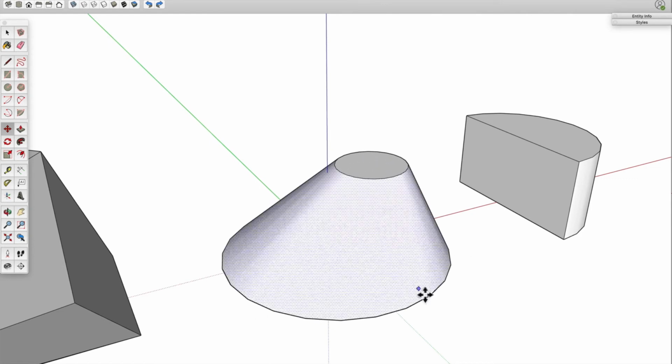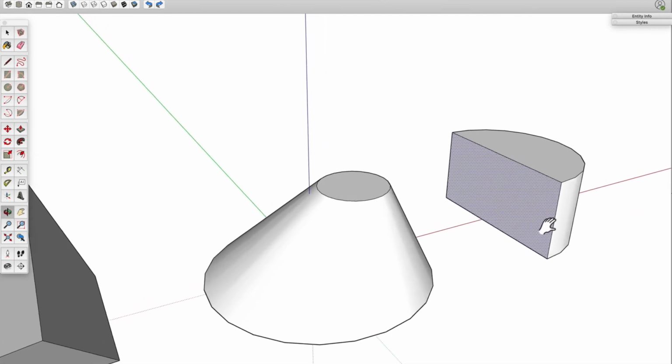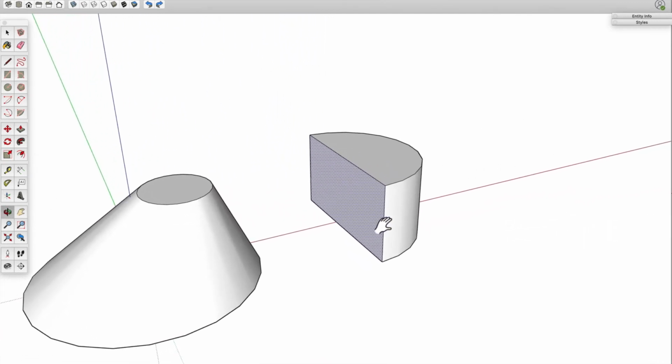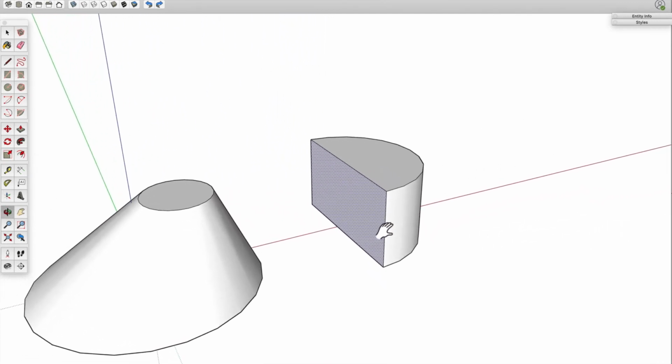So I'll go ahead and click to set that down. Just an interesting set of features for using the Move tool to turn your cylinder shape into some other shapes you might need. Now, the last shape we have over here, let's pan over. Remember, hold down your center mouse wheel and your shift key together to get the pan tool, and then let go of both. So let's take a look at our half cylinder and compare it to how the Move tool worked with the other shapes we've tried already.